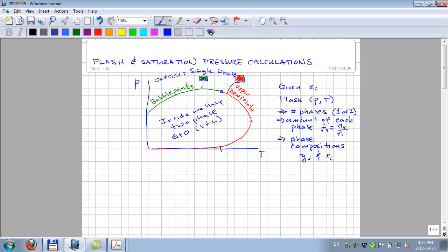But you might pick 0.2 centipoise, or you might be a difficult child and say, I choose 600 centipoise, so anything less than 600 is a gas, and you would have the right to do that because it's an arbitrary definition. It's single phase, but you can say it's gas-like or liquid-like, and you typically key that off of density or viscosity.